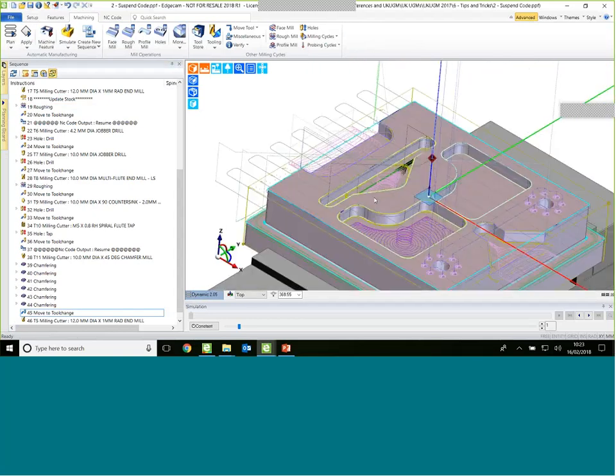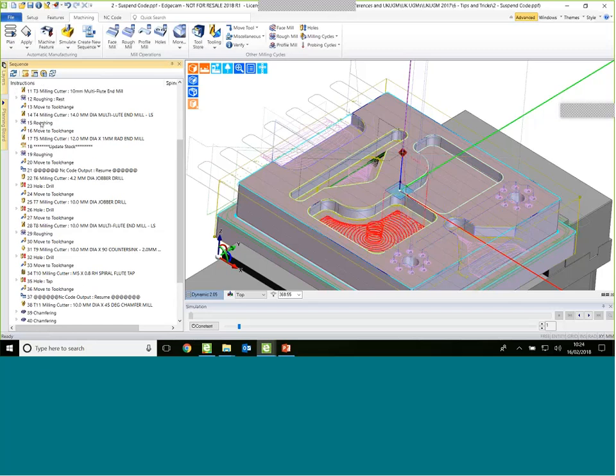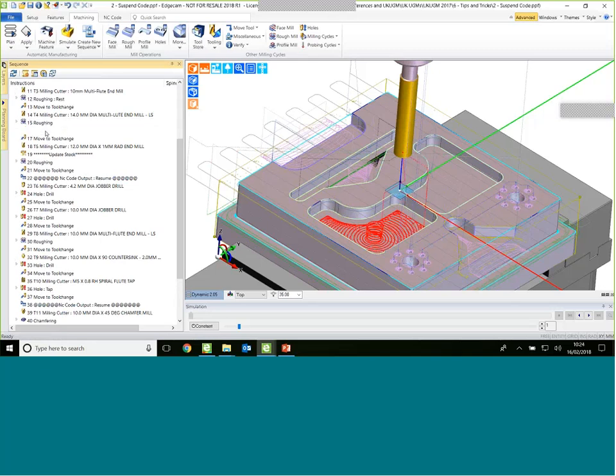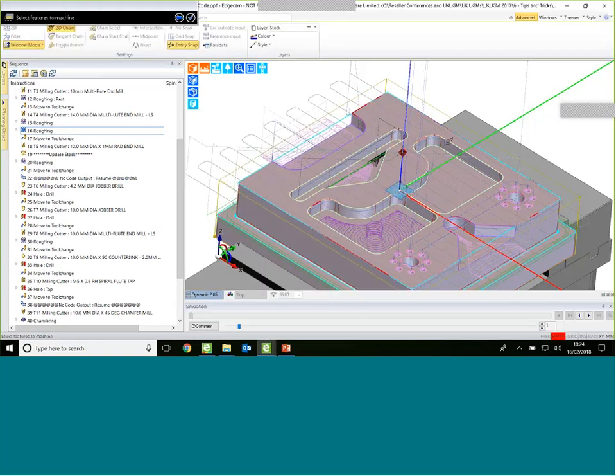The other handy item is all about regeneration, and that's another reason why you have background processing. There should be less regeneration when you do background processing, because of course all the cycles begin in the same spot. But another very quick, easy way to stop the regeneration is to say, turn it off. Simple. So just by clicking that command, I won't get any regeneration. So let me just prove that. If I take cam instruction 15, drag and drop it, no regeneration. Edit cam instruction has now become 16, and ask it to assert itself to the other set of features on this side.